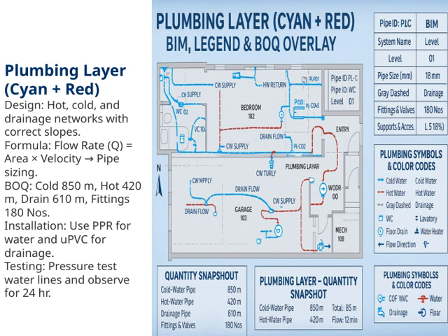Finally, after installation, it's critical to perform pressure tests on the water lines. This involves pressurizing the system and observing it for 24 hours to ensure there are no leaks or weaknesses. Proper testing ensures the integrity and safety of the entire plumbing system. All these elements, design, sizing, materials, and testing, are interconnected and vital to delivering a robust plumbing layer that supports